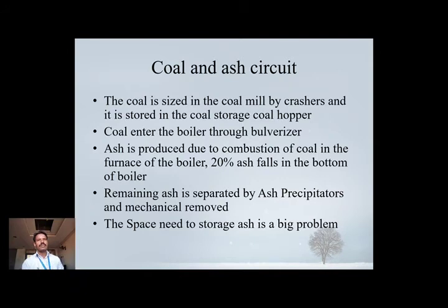Coal generally is sized with the help of a crusher and stored in the coal hopper. Coal enters the boiler through a pulverizer. The pulverizer injects the coal with high pressure, and after combustion of the coal, ash is produced.